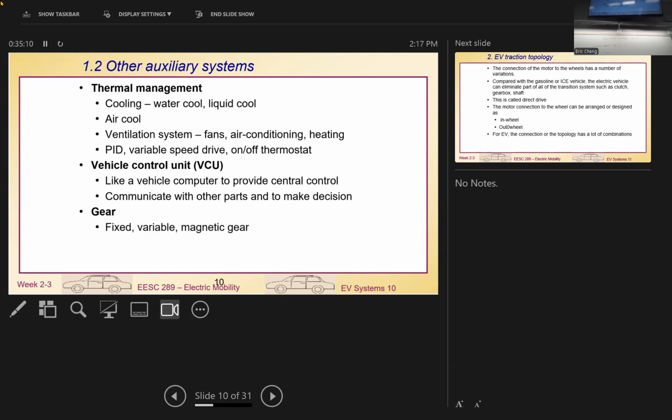Today, when we design an EV, we don't use a single motor. We use distributed motors, two motors, at least, maybe four. So for instance, for a vehicle with 200 kilowatts of power, if you use four motors, each motor becomes much smaller, with a lower profile. But if you use one 200 kilowatt motor, it is so big that your vehicle height will be much higher. We don't like that. We prefer streamlined bodies with a low profile, so we use distributed motors, each one small, and then we use a good cooling system to cool them down.